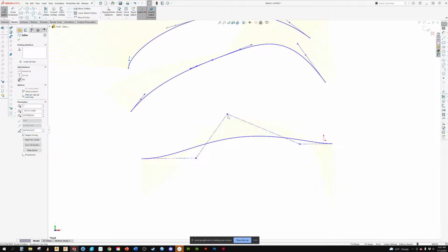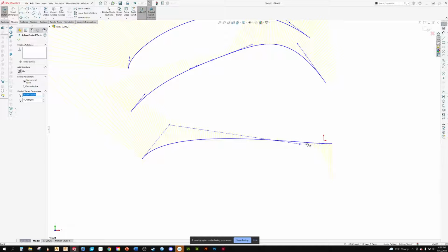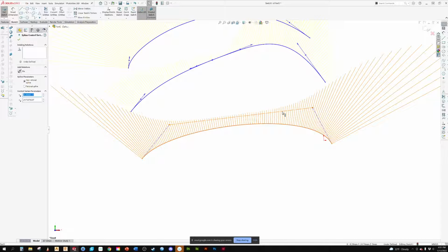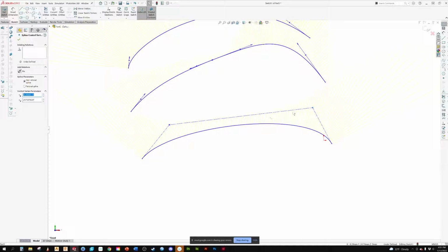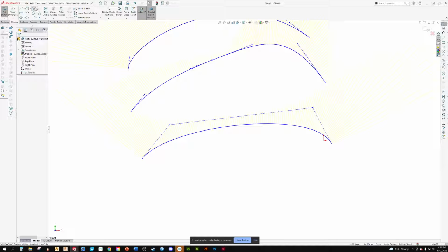In order to achieve that, let me just come in here. Right here, if we match this with this dot, that's equivalent to having the tangent control. So the best I can ever achieve with this line is tangency, because I don't have the second control point that controls curvature. So if I want to get curvature on both sides, what I would need to do is, you know what, it's just easier for me to draw another one.